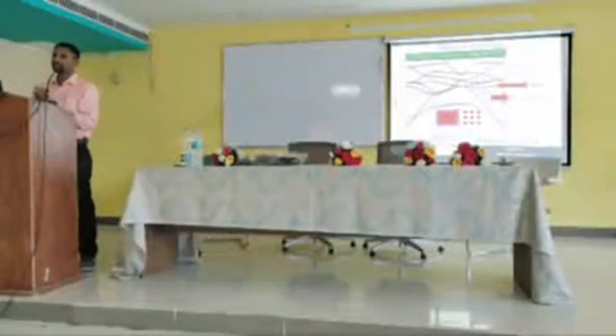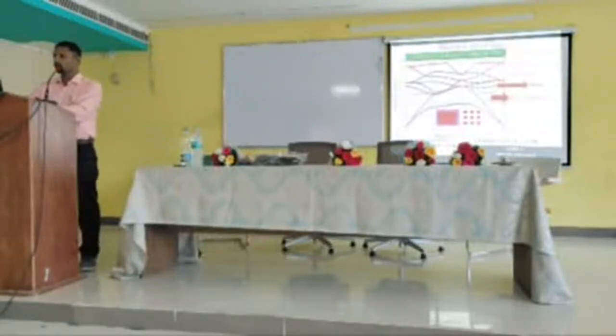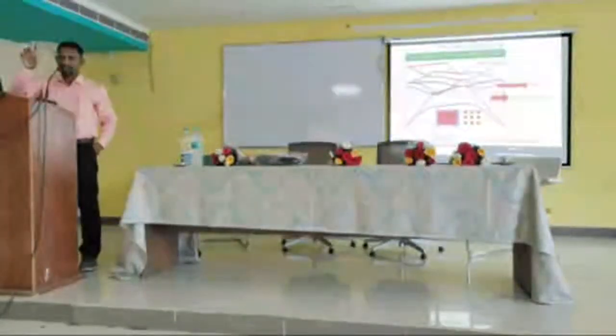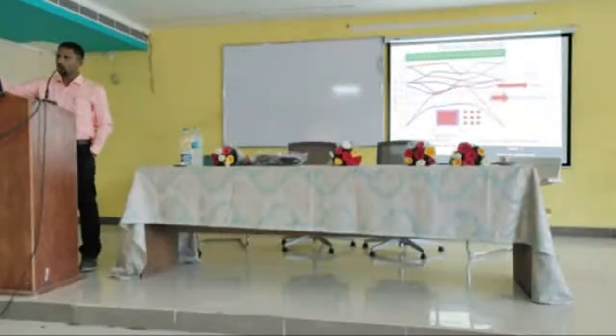Let's come back to our discussion. In the structure, if there is only one wavelength of light, that is called a mode. A group of wavelengths of light is called a band. The non-allowed wavelengths of light, the non-allowed light signal, is called the photonic band gap, which means that in the periodic structure, in a certain range, the signal is not allowed to propagate.